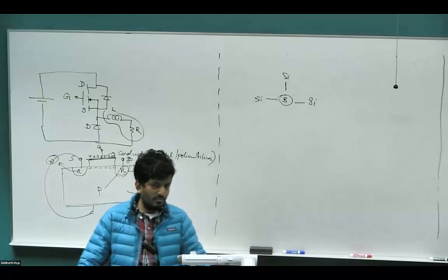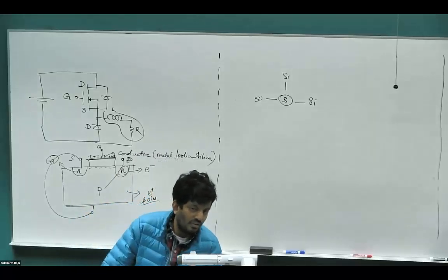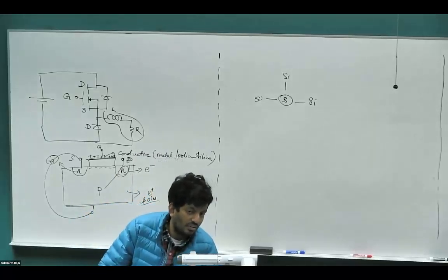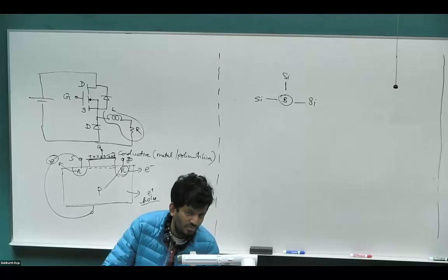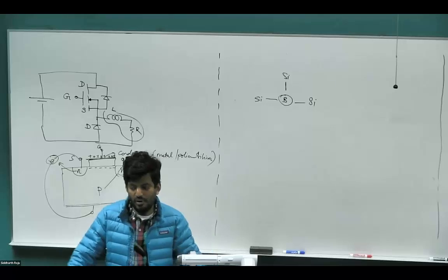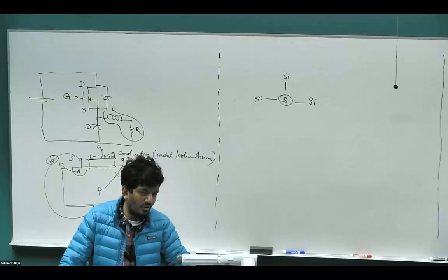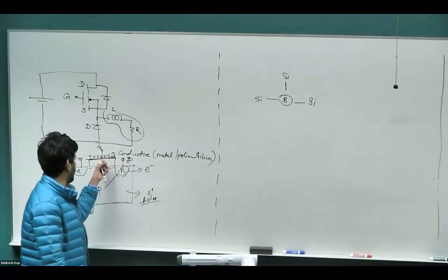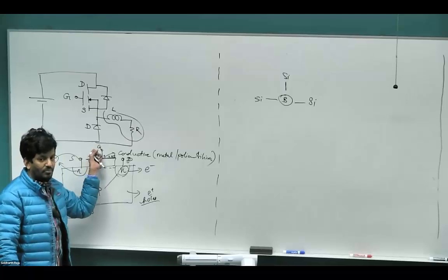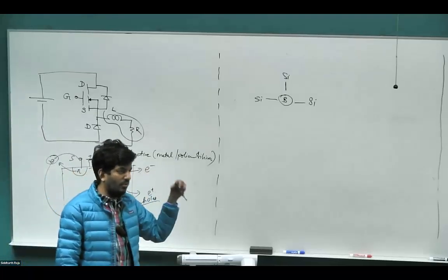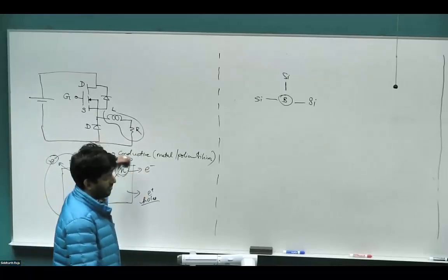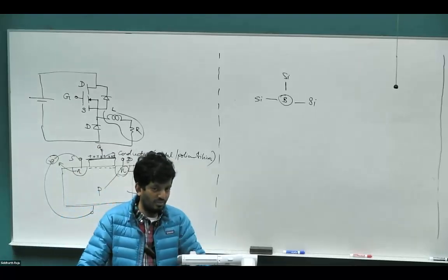Any other questions? Yeah. Use a BJT in power applications? It used to be used, but no longer, because basically the problem with BJT is it's a current control device. But in power electronics, we typically want to have voltage control on the gate side. So here we can control the conduction of this by the voltage that we apply here. In a BJT, you would have a channel you would have to control using some kind of current source.